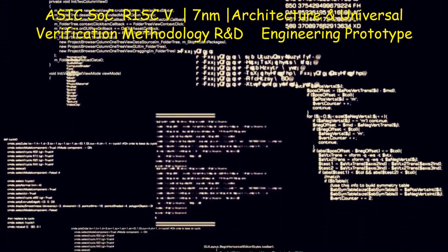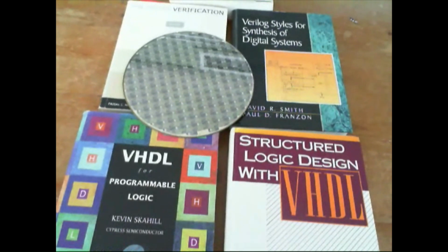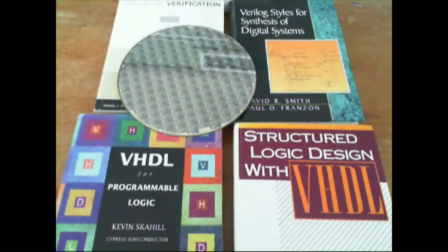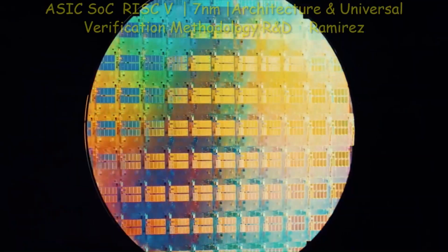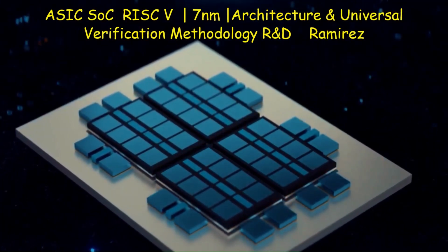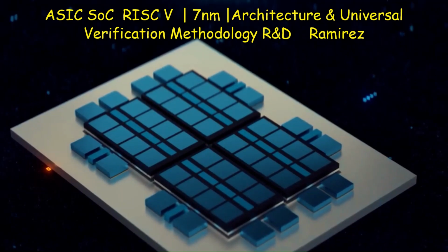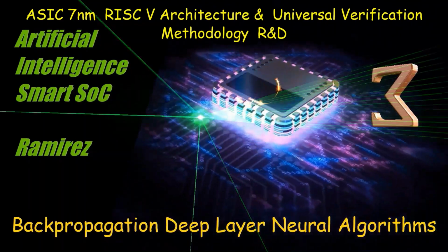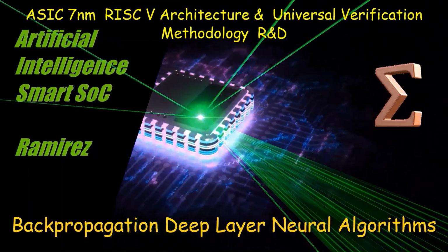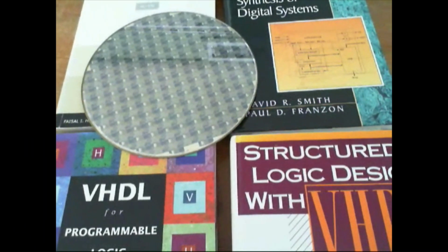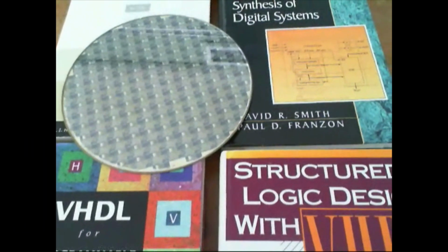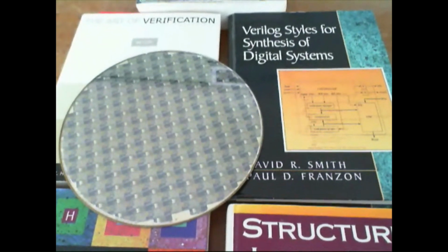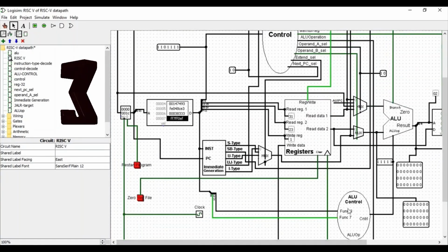CVC checker is a device-level static verification system for quickly and easily detecting common circuit errors in CDL, circuit definition language, netlists. So I ran tests on the final design and found no errors at all. All of my ASIC projects go through a very rigorous verification methodology.